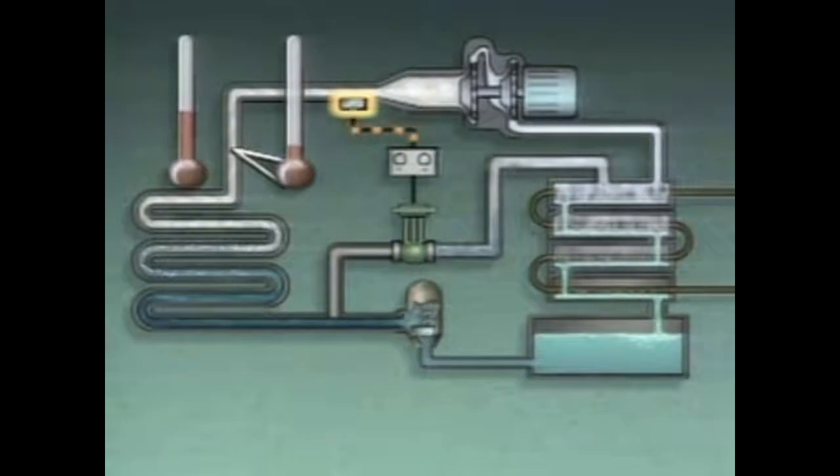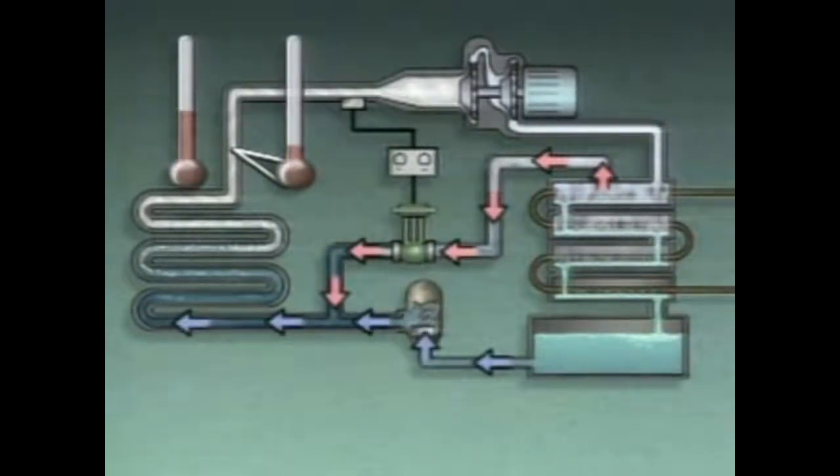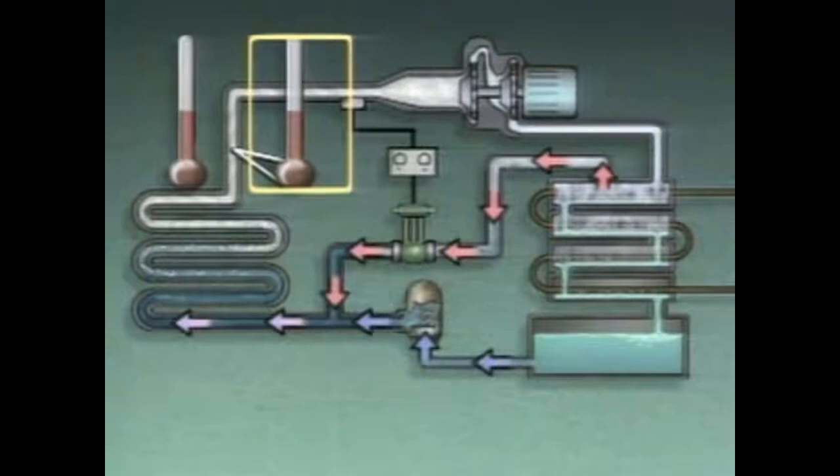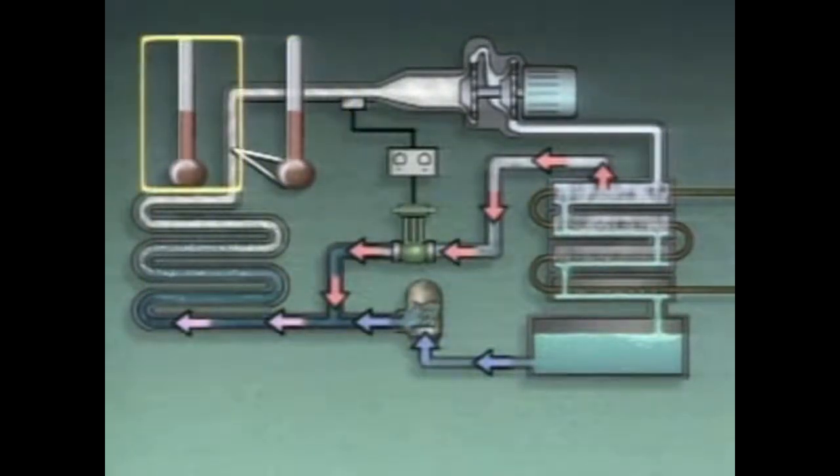controller, which in turn sends a signal to the bypass line control valve, causing it to open slightly. This allows some of the refrigerant from the discharge of the compressor to be routed to the evaporator. This warmer refrigerant mixes with the refrigerant leaving the expansion valve and increases its temperature. As a result, less heat is removed from the substance being cooled, and its temperature increases back to the desired value. Another way that refrigerant flow can be controlled in refrigeration systems that have centrifugal compressors is by using dampers